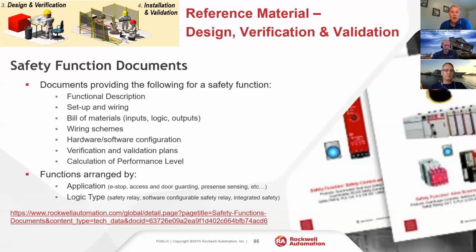If nothing else, for a lot of the implementation of safety circuits to today's standards, this should be used. These functions are arranged by application as well as logic type. For example, I need a door interlock and I'm using a safety relay, or I'm using a door interlock with a software configured safety relay, or even a door lock with a safety PLC. It will literally give me these choices and allow me to take advantage of these pre-done, pre-set up safety functions.